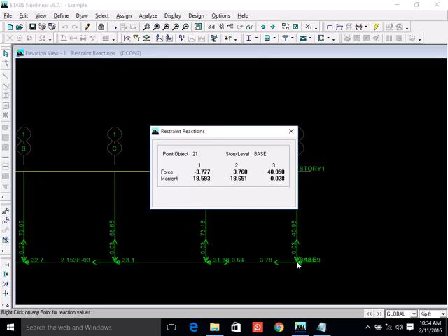So you see that only a person who has good understanding of these basics of structural analysis can understand this and pick the errors. He can find out the errors. If you don't have biaxial bending at the corner column, then there is something wrong, right?